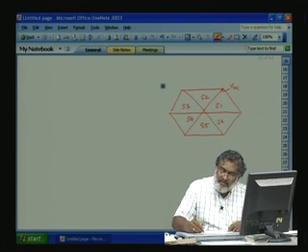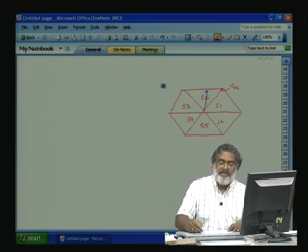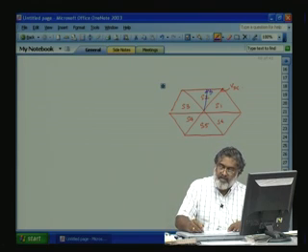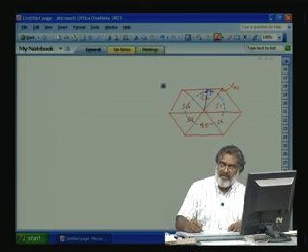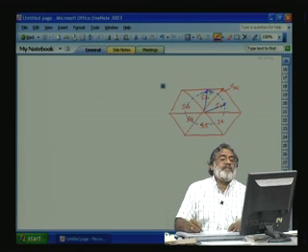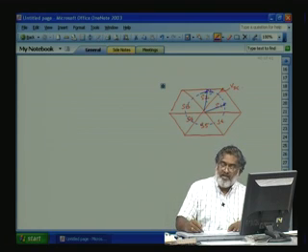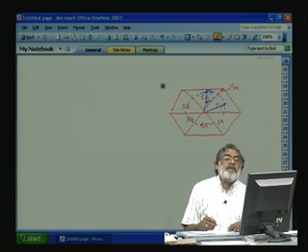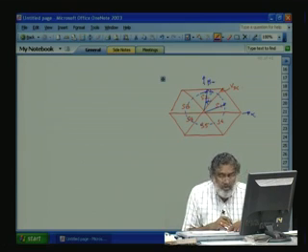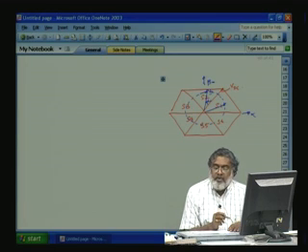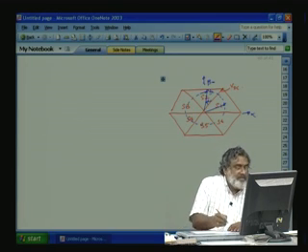Now, let us say this is our new Vs. It is making a circle at uniform speed. See, previously it was in sector 1, we found out, now it is in sector 2. In sector 2, alpha has to be measured from the start of the sector. But our V alpha is in this direction, V beta is in this direction. So, how do you represent this equation?